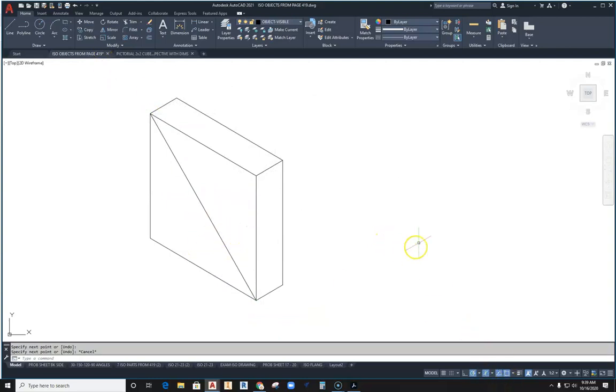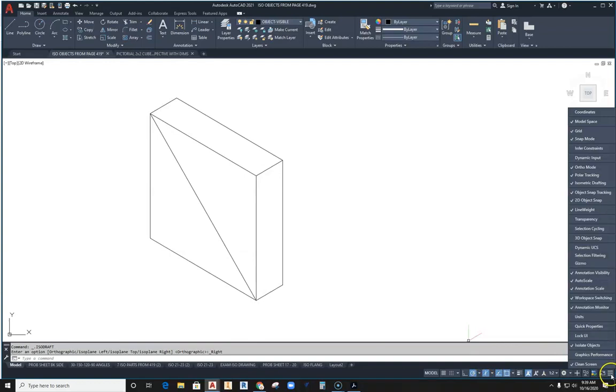My ISO circle cursor is active. If not, your cursor would look like this. You're not going to have the ISO circle option when you go up here to your axis end. There's no ISO circle option. So what do you do? Well, you've got to get that cursor turned on down here, so you have your isometric cursor. If for some reason this disappears, you don't see it down here, you can access it by these 3 little lines over here, and then go find your isometric drafting tool right there. Isometric drafting will turn that back on.